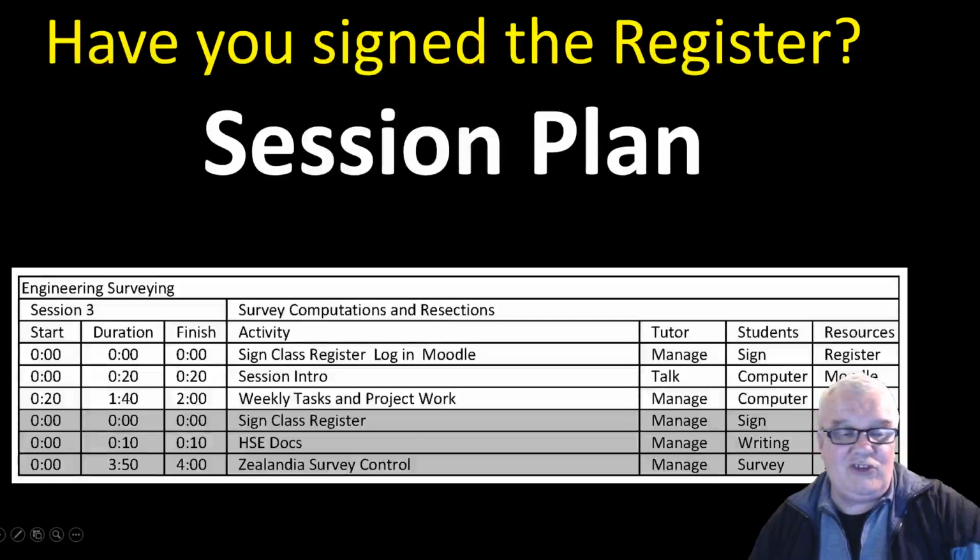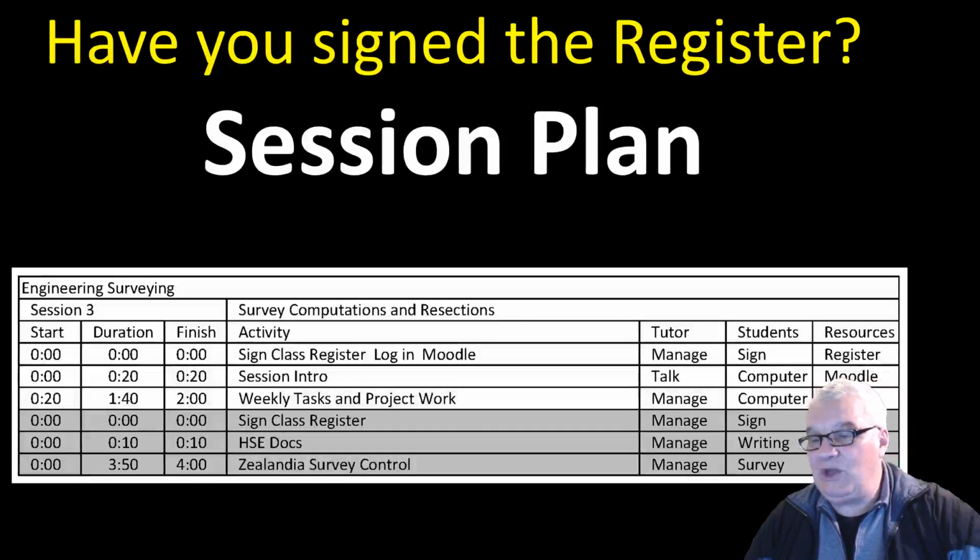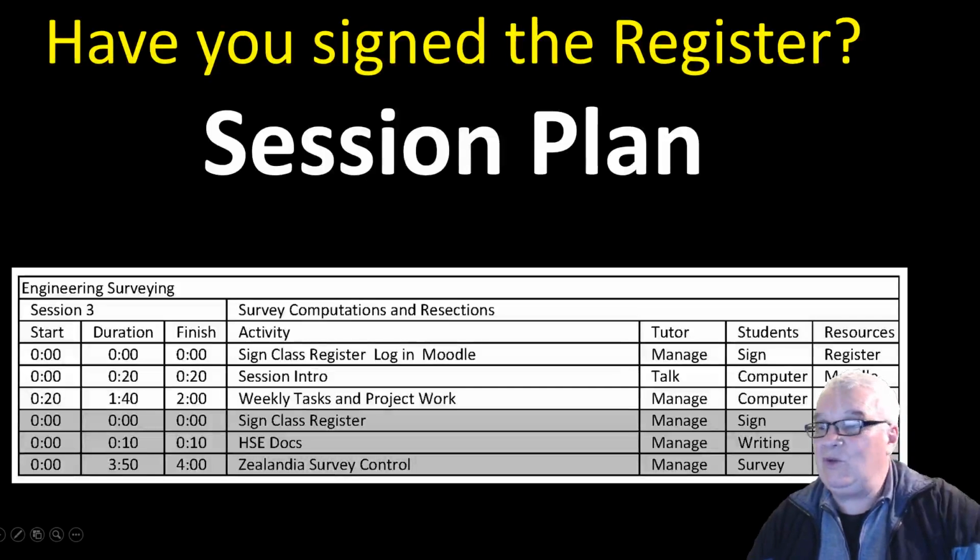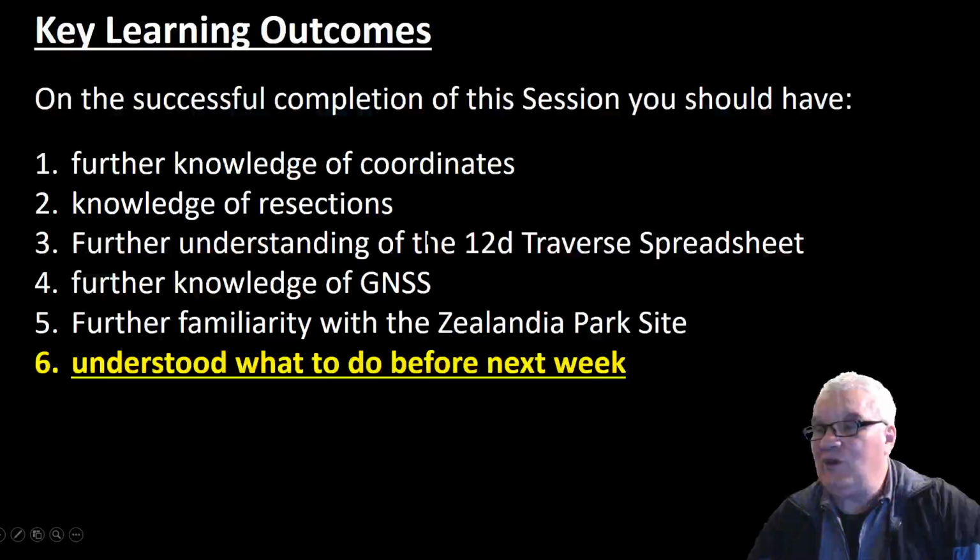Generally, the process of surveying is to do your research, establish your control, establish any new marks, and then do the detail. It might be topo, or it might be some cadastral boundary work and what have you. So moving on from there.